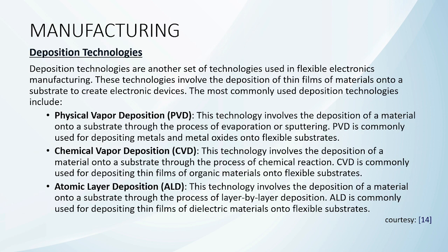Deposition technologies are another set of technologies used for flexible electronics manufacturing. These technologies involve the deposition of thin films of materials onto a substrate to create electronic devices. The most commonly used deposition technologies include physical vapor deposition. This technology involves the deposition of material onto a substrate through the process of evaporation or sputtering. PVD is commonly used for depositing metals and metal oxides onto flexible substrates.